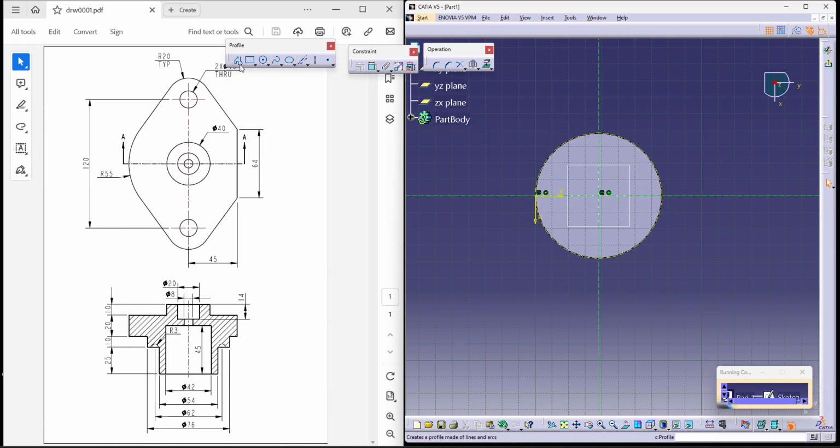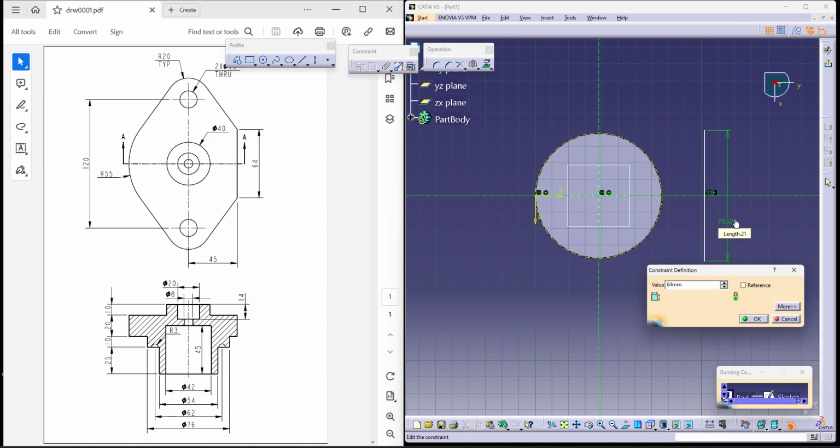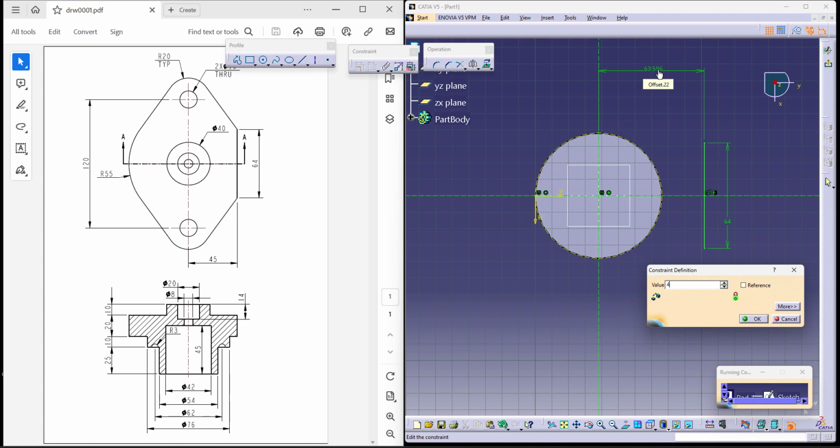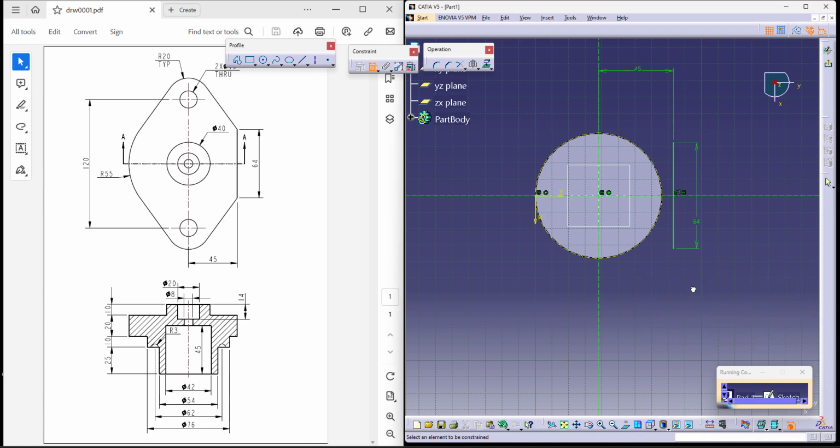Since we have taken our references, let's start making the model. Under line, we have a symmetrical line. This is an equally distributed line on both sides. So I'm using a symmetrical line to maintain an equal distance on both sides, and obviously maintain the dimensions provided in the drawing, which is 64 and 45 from the respective center, which is the circle center. In the same manner, there are two arcs over here as well as 55. So let's try to take 55 first. It's a little easier to do so. This is 55.